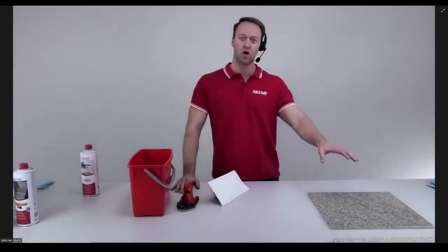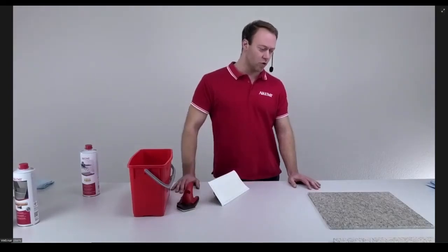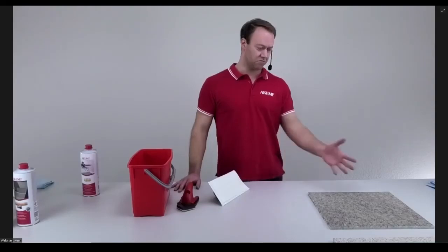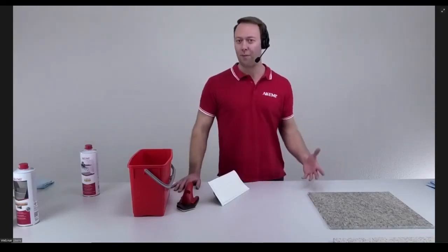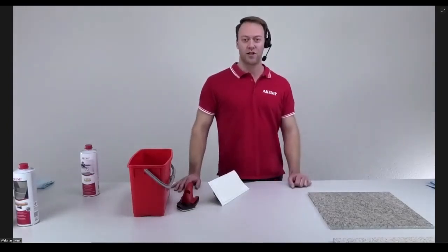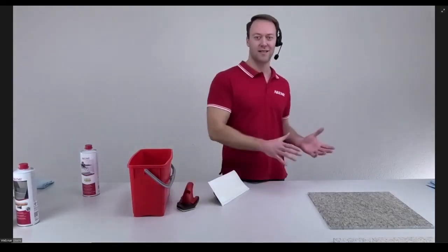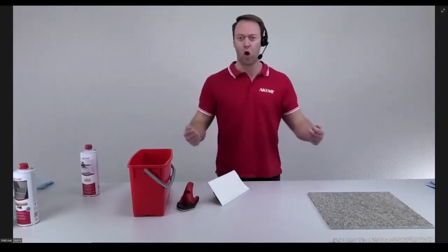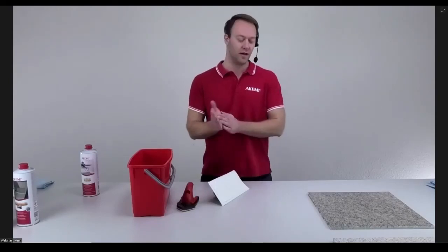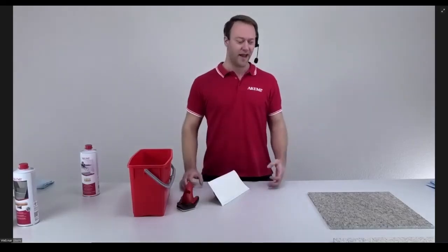When it comes to hard stones, like granites, usually here one good application with enough material, like what I just did, is good for many years. Then of course it depends if it's inside, outside, if it's a kitchen countertop where you always have heavy cooking, oil spilling, a lot of stains. Then maybe you have to do a treatment more regularly. But usually on a hard silica-based granite, one good application is good for many years.